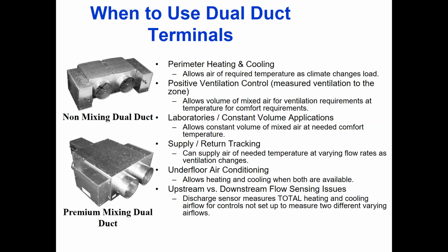Now, on the positive side, this allows you to do daytime heating if you need to, and you do not have to have any hot water coils in the zone or baseboard or anything like that. I do it all with the air side. But the problem is, from the energy standpoint, I'm taking air that I paid to cool and air that I paid to heat, and then I'm mixing them. Not super smart from an energy standpoint. In fact, for the past, I don't even know, 10 or 15 years, the energy codes all prohibit you doing this. So you're never going to see this on a new install. You only see it on existing systems.